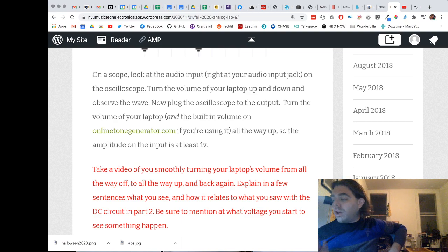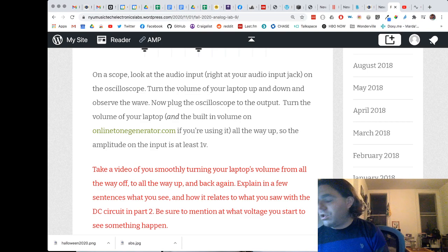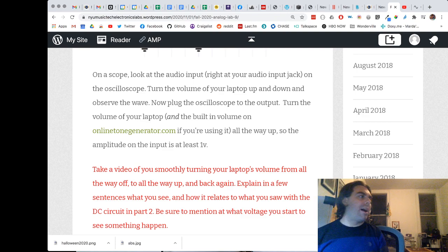You might have to adjust the sensitivity on your oscilloscope so you could see it clearly happening. The settings that worked for me were 0.1 volts on sensitivity 1 and X5 on sensitivity 2. So basically, I have each horizontal line as 0.5 volts, and you should be able to see a very clear clipping line happen.